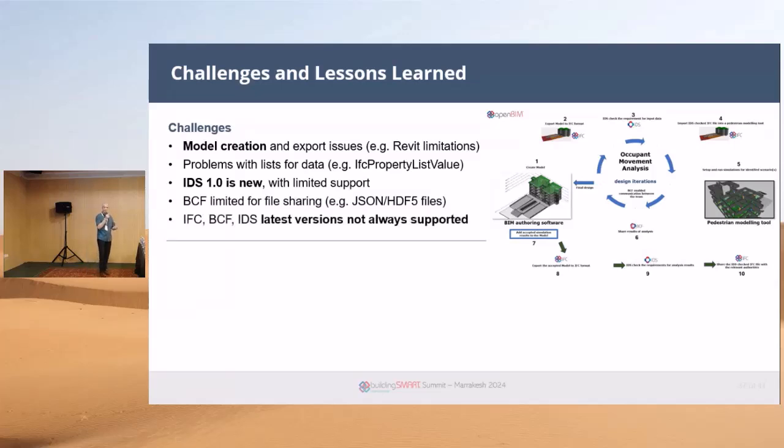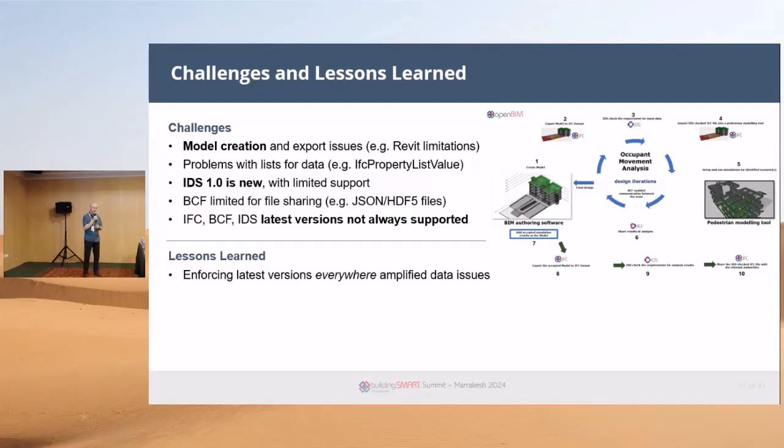And then again, we had the same issue with different file versions not being supported properly either. So some of the key lessons learned in that process. Well, enforcing the latest versions of the different schemas that we chose to do, IFC 4x3, IDS 1.0, etc., amplified some of the data issues. We did overcome them, but we had to manually edit some files in some places to complete that whole loop.